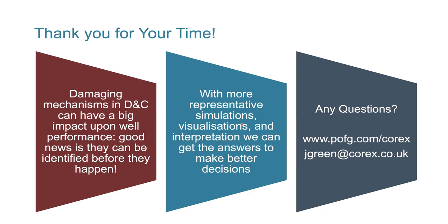And in the field, we only find out when we drill two wells and see the difference. The whole beauty of having lab simulations is you can muck around in the lab. Sure, it's for a cost, but one, two, three simulations in the lab don't cost what it costs to drill a well. So density, overbalance, exposure, length of time of exposure. If a well is going to be shut in for a year, do you do a test where the mud is exposed for a day, or do you do a test exposed for weeks or months? We could see very different results.